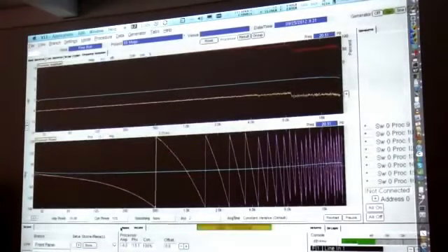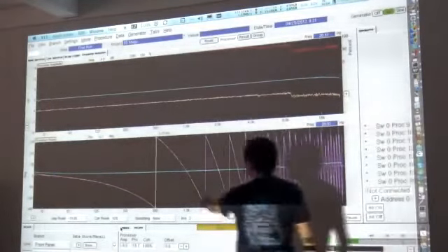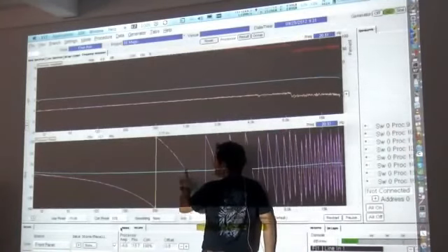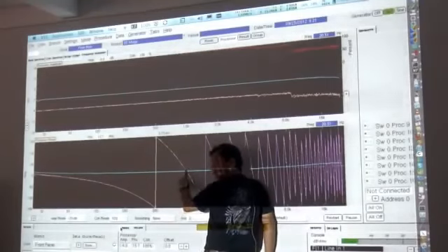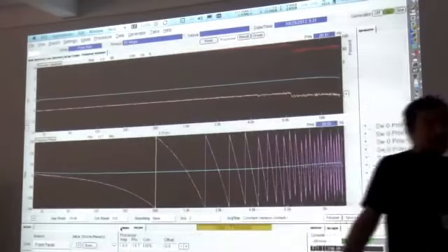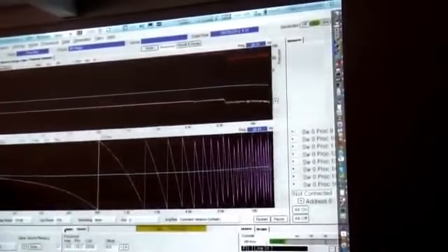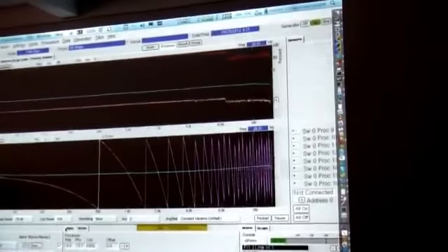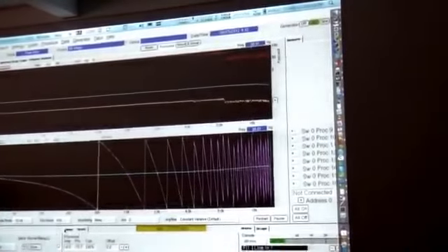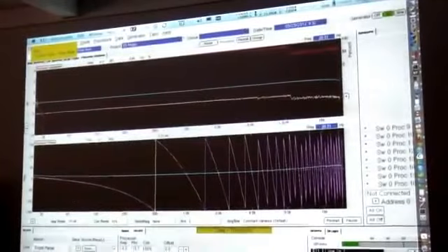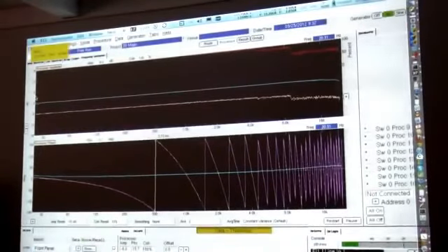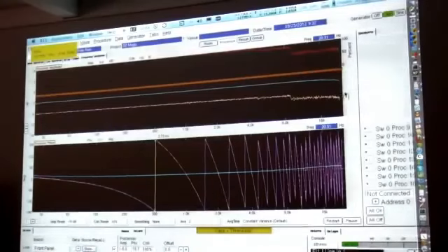Okay. So what happens at this frequency? Summation, plus 6 dB. But 6 dB is not possible, because they have a 6 dB difference. One signal is 0, in linear is 1. The other signal is minus 6, in linear is 0.5. So the maximum summation is 3.5 decibels. The maximum summation will reach this line.